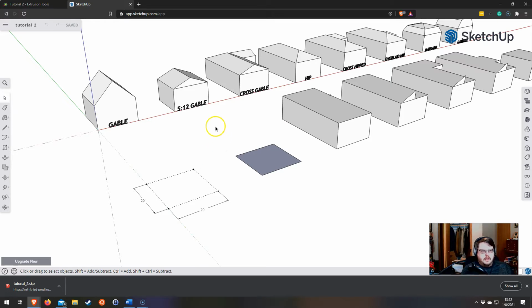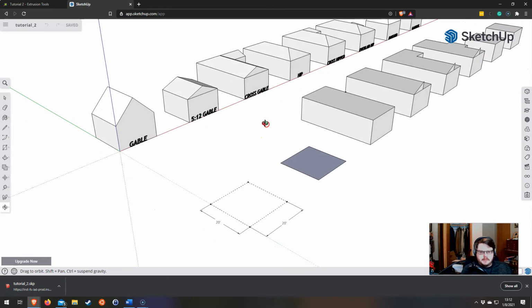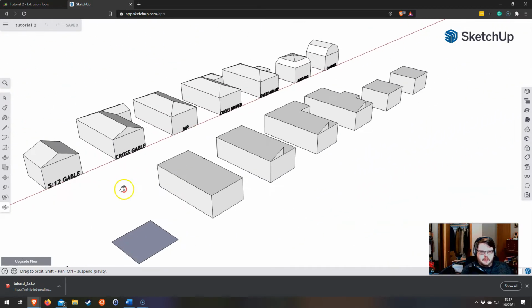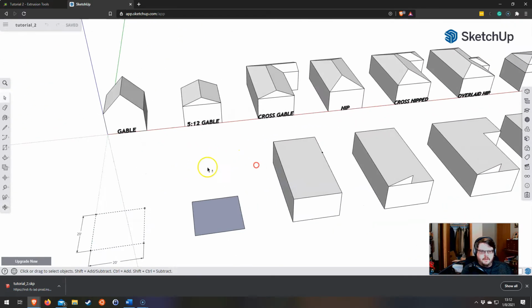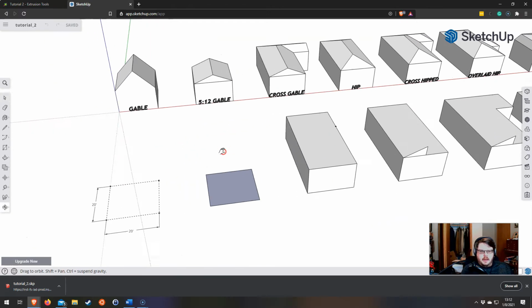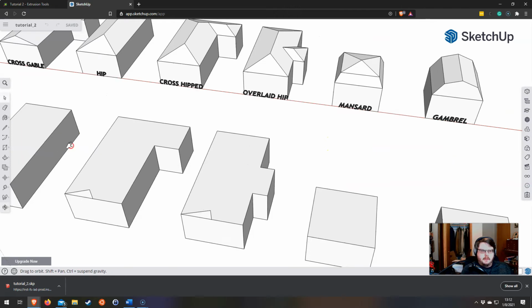Now you'll notice if you keep holding the middle mouse button and then press the shift key, it turns into the pan tool. So that's how you move around horizontally. So eventually you'll just keep one hand on the keyboard, one hand on the mouse, and then you'll just seamlessly move around the map.